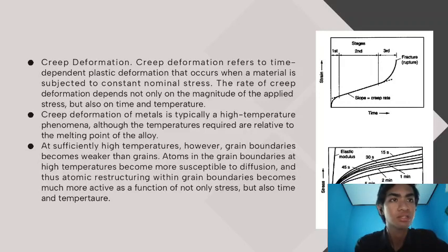The stress that causes a specified strain at the temperature is then called the creep stress of the material for those conditions. Other times, equal strain results for a given temperature are plotted on a stress-time graph. When a creep test is continued until the specimen ruptures, the test is often called a creep rupture or stress rupture test, and the results are reported on a plot of stress versus time to rupture.